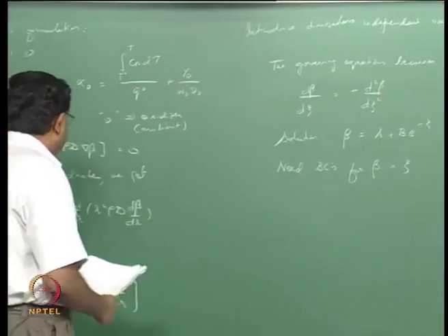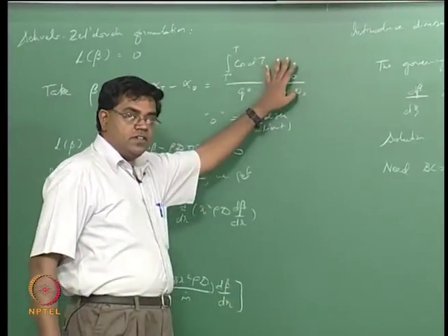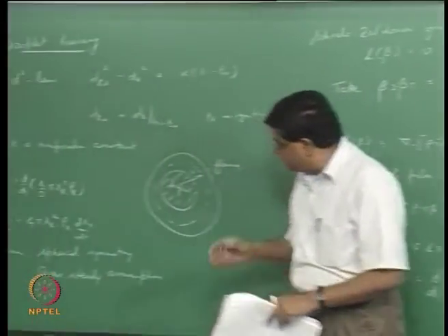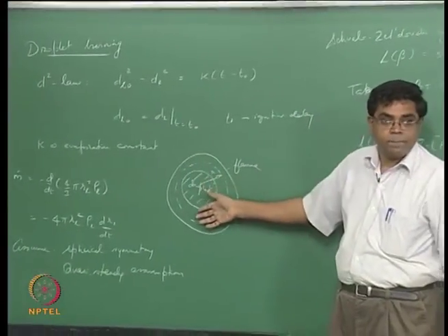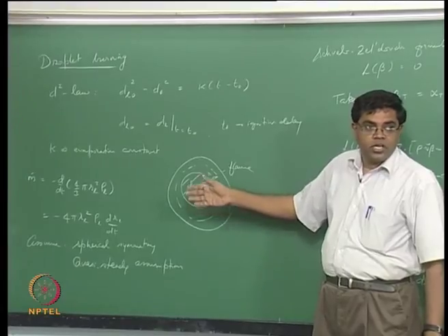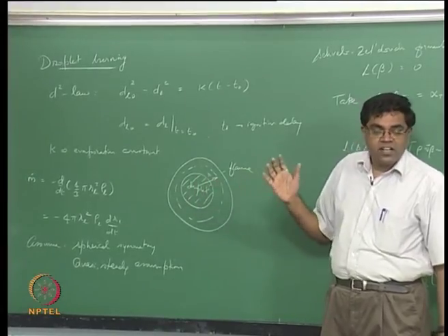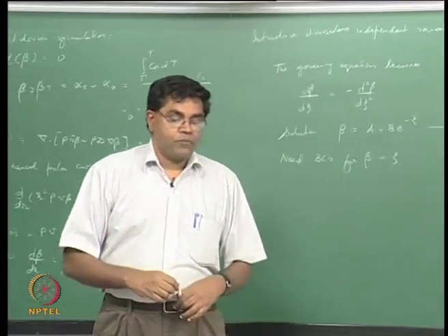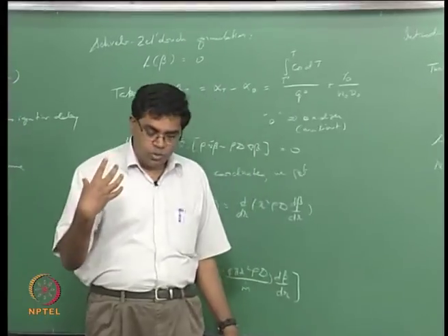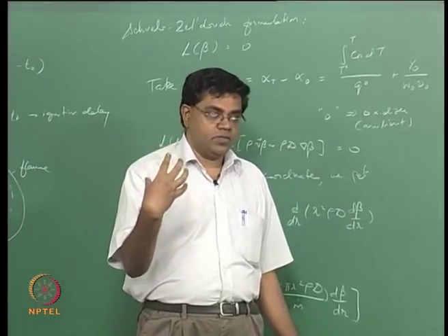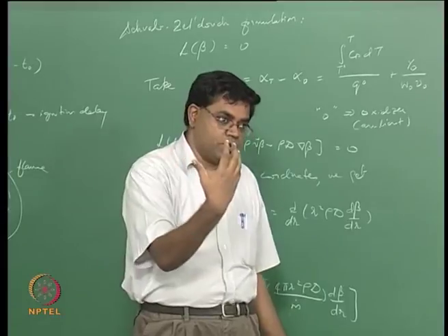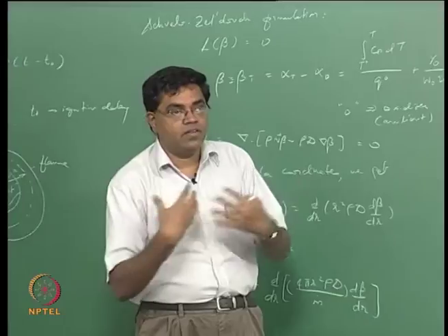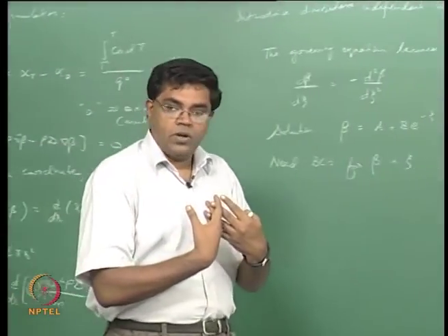So as far as the species is concerned, what we know is that the oxidizer cannot penetrate the liquid surface, alright. Now this need not necessarily be true, but suppose that you have a liquid droplet which is intact and it is going to produce gaseous fuel, it means that the gaseous oxidizer does not penetrate the liquid.